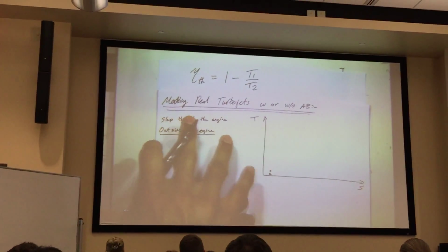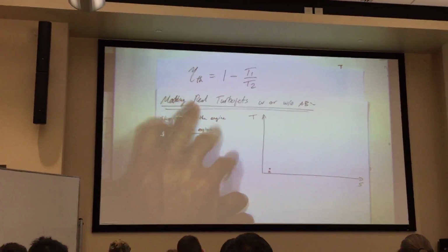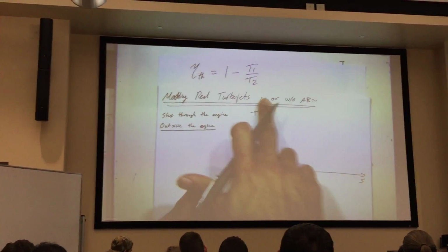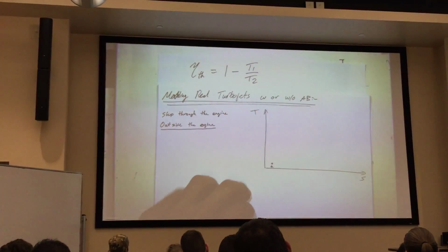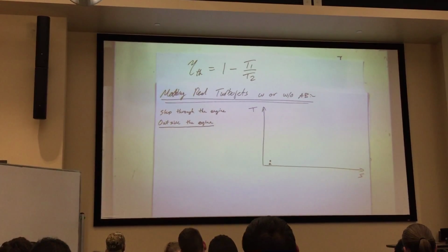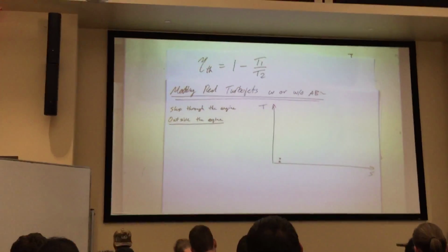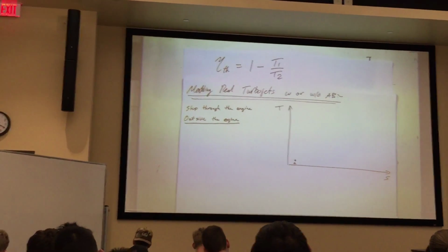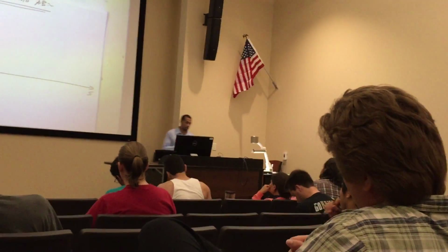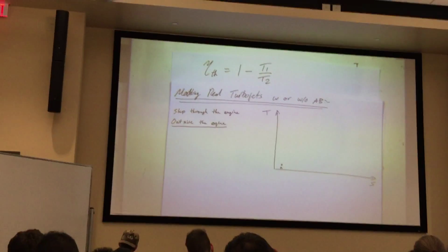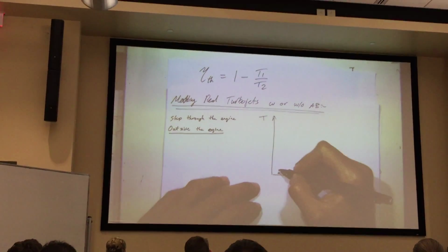If I have a turbojet that is real, it's not ideal, without an AB. Without an AB is easier because it's sort of a straight curve through the CD nozzle, turbine through the CD nozzle. But with AB, we have that additional expansion. So we'll draw the with AB.